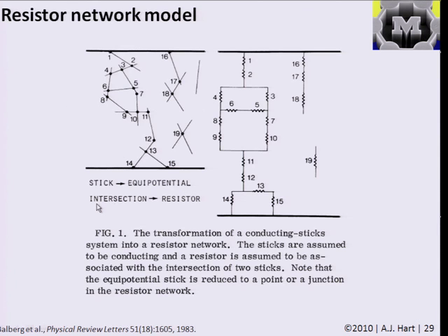And another model, for example, can be derived by mapping one of these random networks as a resistor network. And here, you see a case where you've just formed a percolation network across the gap. And if you map out that each structure has an inherent resistance, and there are also contact resistances between the structures, you can see that you have a combination of serial and parallel paths.